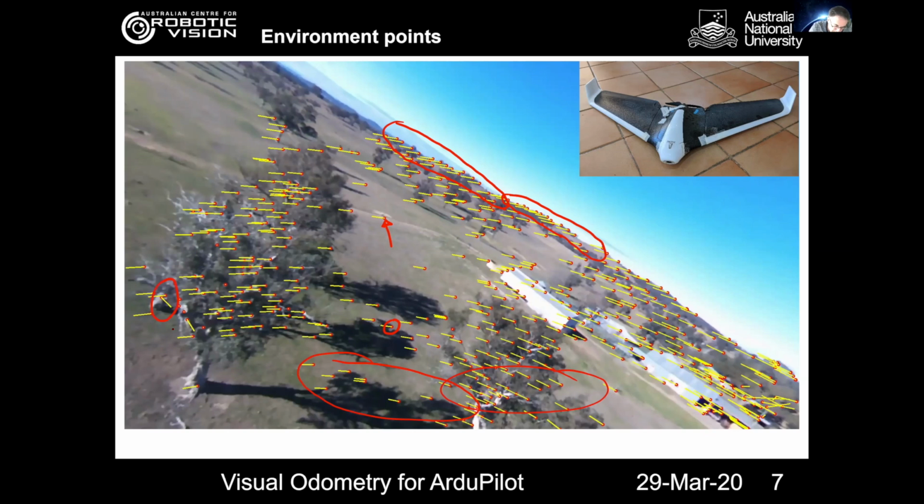So you can see where there's false matches over here where the algorithm has failed to pick the actual translations. And we've done quite a bit of post-processing here, if I remember. Peter can tell me more in a moment, but we've sort of cleaned up as much as we can of the false matches. You can also see over here, we've got a few false matches, particularly around the edges of images where you get distortion from the lens, so lens distortion, so your motion models start to fail, all of those sort of things that cause you problems.